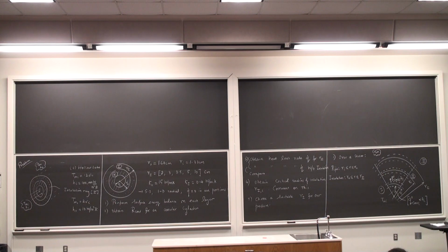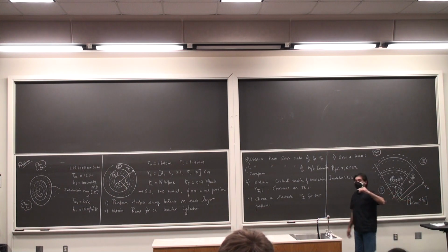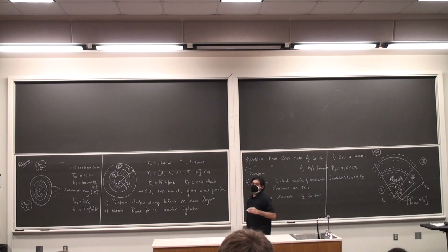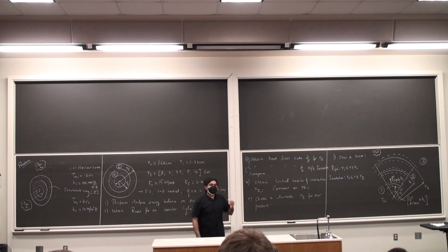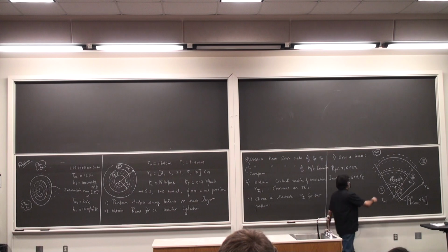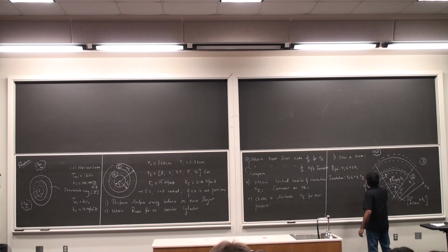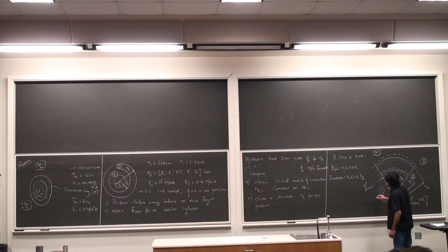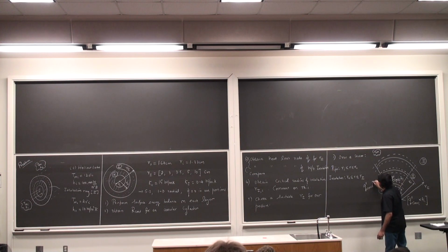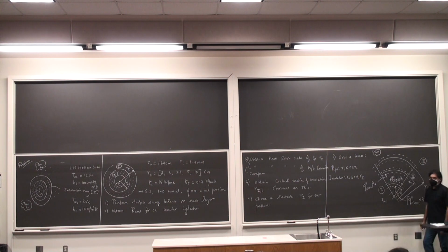It is obvious that if there is no energy generation taking place, the conductive flux will be a constant, right? So which means that I just draw this arrow here. This is Q double prime conduction I, or conduction O, okay, if you want, multiplied by the area A naught. Okay, this is for the material of thermal conductivity K suffix T. This goes into the insulation ring.